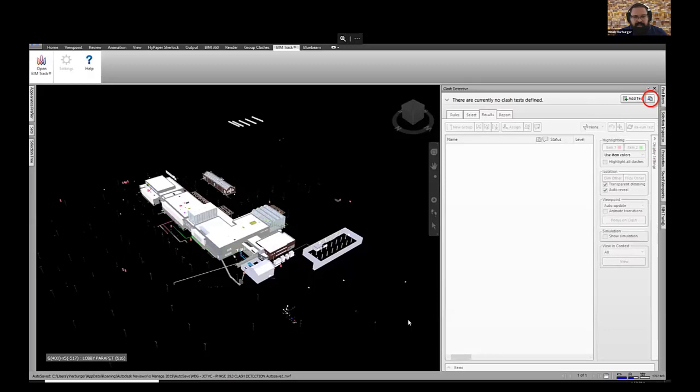So when you come into Navisworks, if you don't do all this template setup, it can take a long time to get started. Unlike Revit, where you can just start a project using a template, Navisworks doesn't have that new project from template.